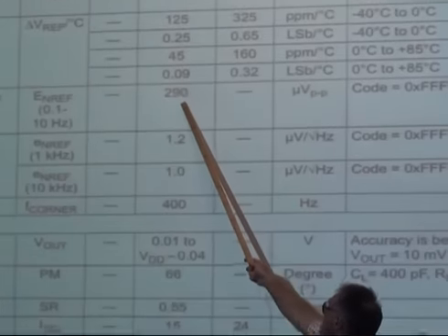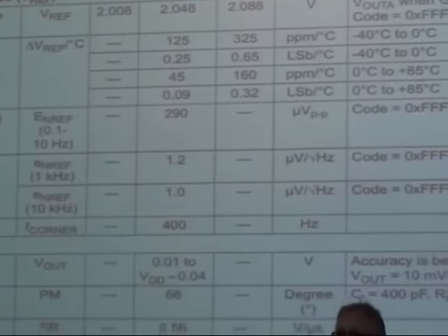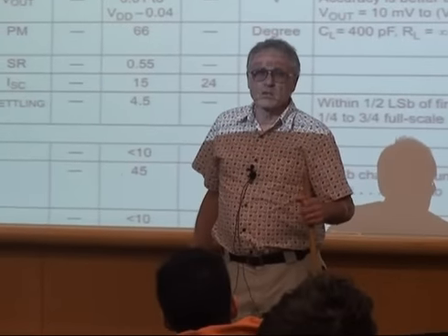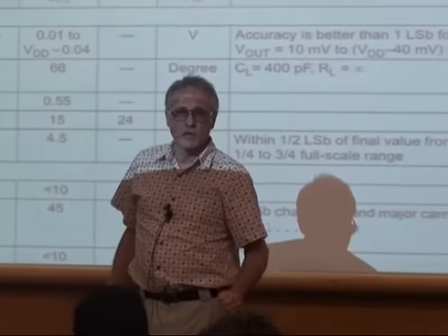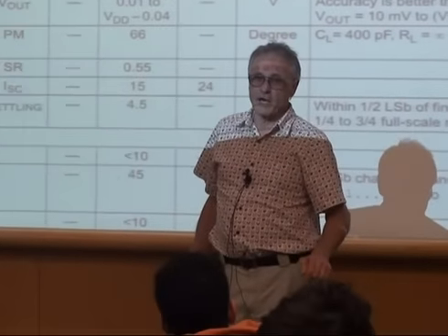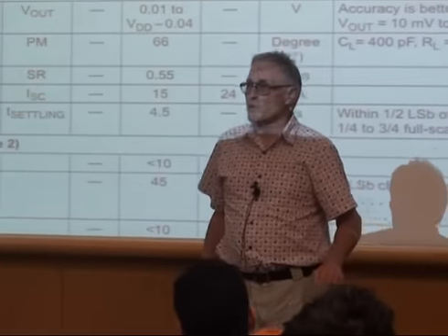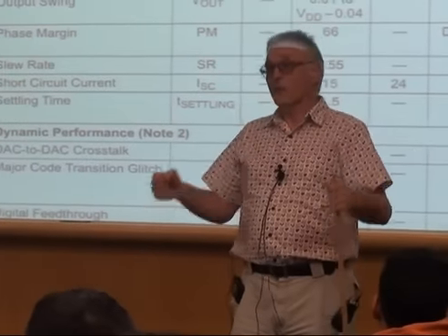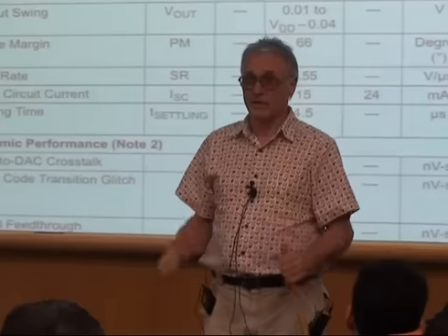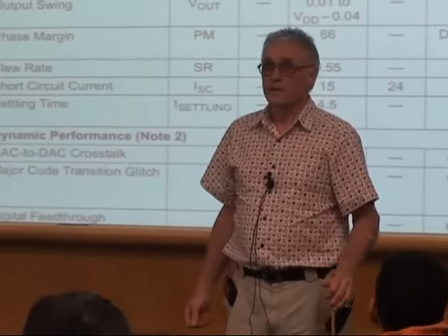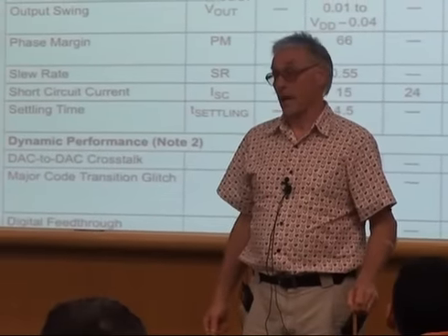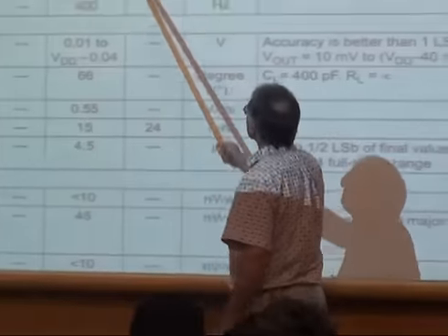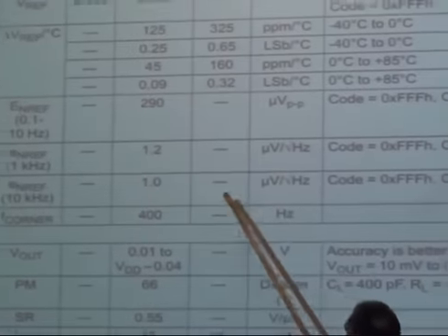You're going to hear this noise? 290 microvolts of noise is actually a fair amount of noise. Well, there's two reasons why you're not going to hear it. One, your frequency response at 10 hertz is lousy. You might be able to feel it shaking your chest cavity, but you're not going to hear it. Secondly, the speakers have zero gain at 10 hertz, or very close to it. So that's not so much to worry about.